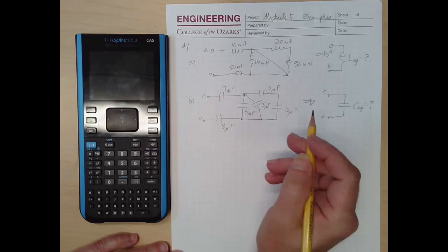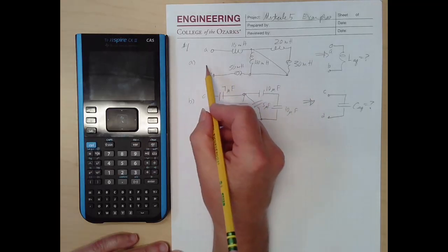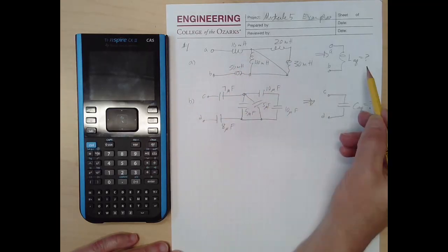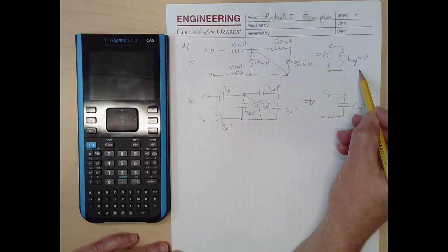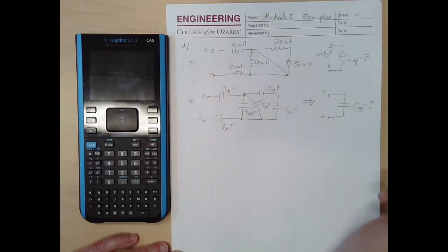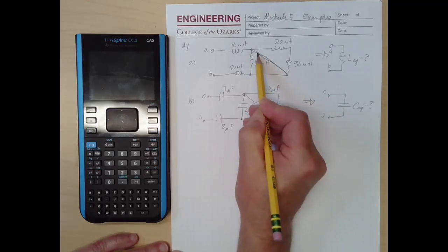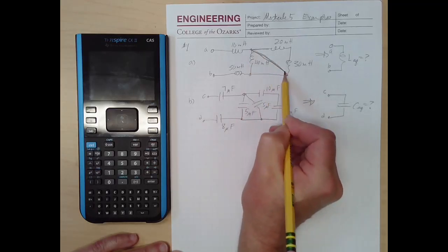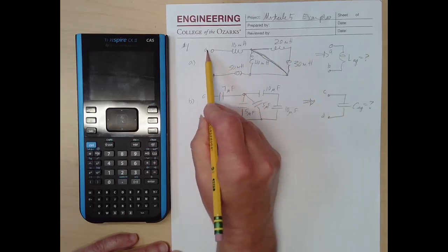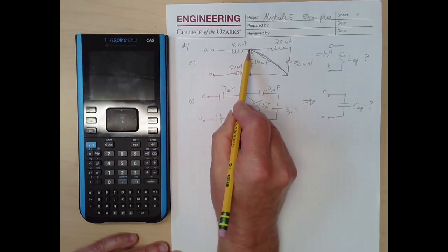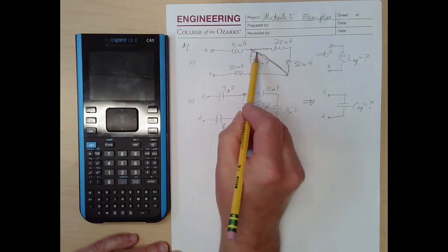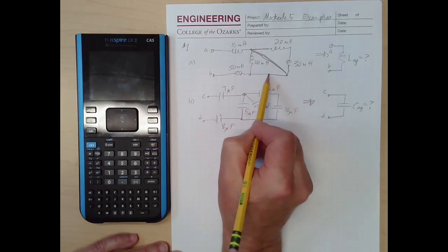So this is stuff we did in physics, but for number one, we're going to take the circuit and combine it into an equivalent inductance, just one inductor between the two terminals. So looking at this circuit, we need to think about parallel and series combinations, and we need to watch out for tricks, right? This one is a tricky circuit because notice this connection here is shorting out these two. If we had current flowing this way and it decides whether it's going this path or this path, all the current will go through this path, right?